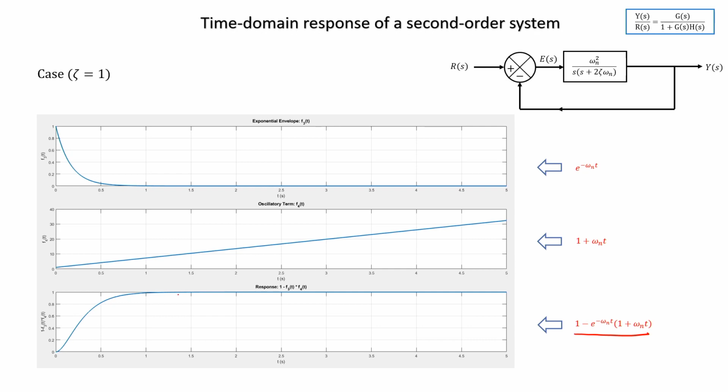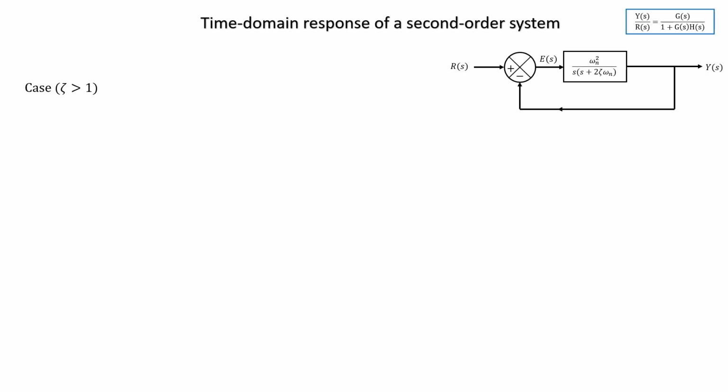However, you see there is no overshoot here. In the previous case we had overshoot, but here there is no overshoot, and one more important thing to notice is that there is a U shape kind of a thing here. So, you will see that this thing will not remain when we go for the case when zeta is greater than 1. For zeta greater than 1, again the expressions will now see I am writing it as zeta square minus 1 instead of 1 minus zeta square.